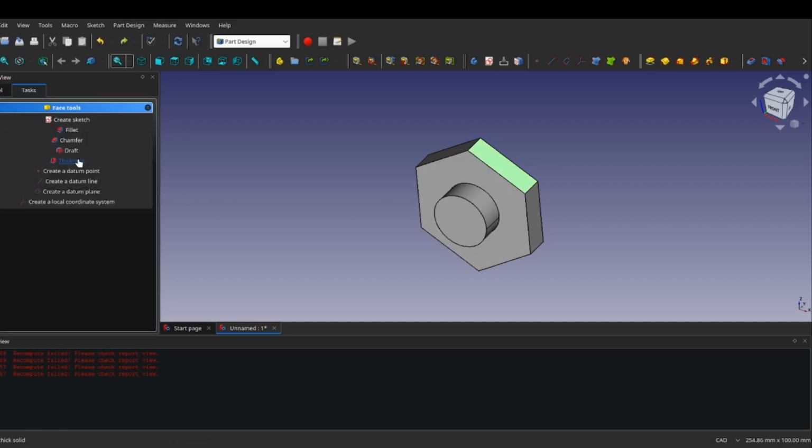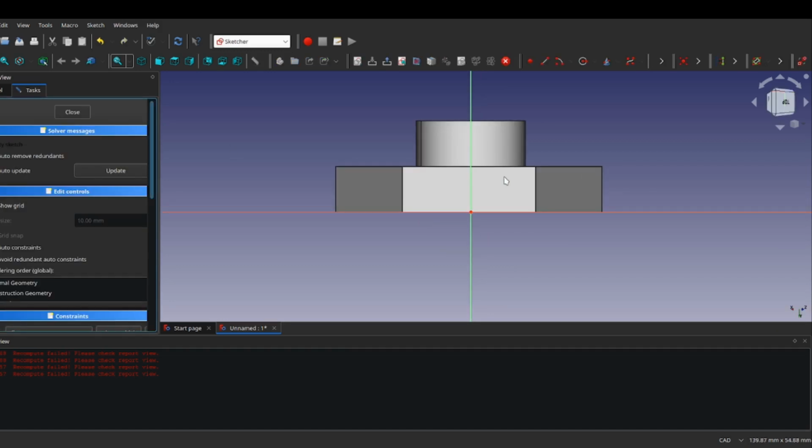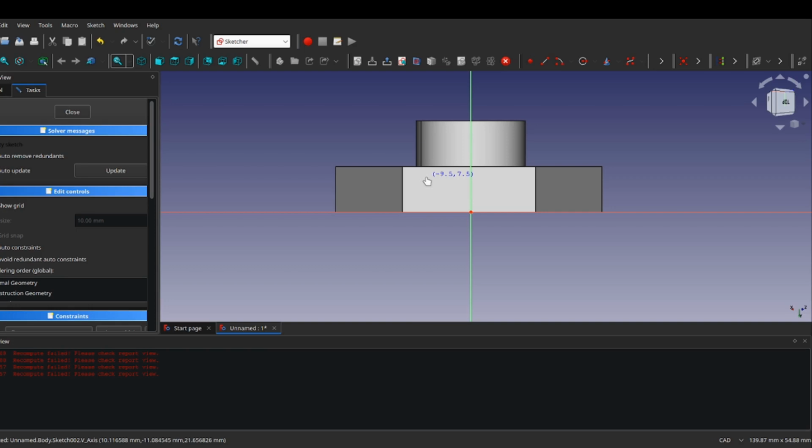Now I'm going to go over here. I'm going to create a sketch on that face. And that's why it's facing me. That face only is facing me. I'm going to put a poly design on here. Let me put the rectangle on here. I haven't used that one. The favorite rectangle. Let me put a rectangle right here. Remember, the rectangle is on that face that I selected. Whatever you're doing, FreeCAD, and I guess the other 3D packages too, it better affect just that face. See, it was a revelation to me.